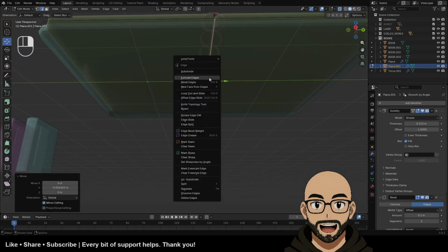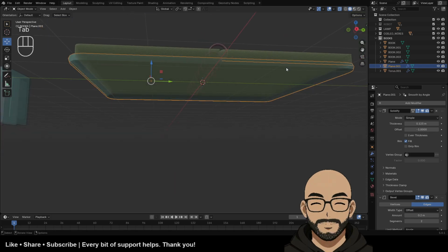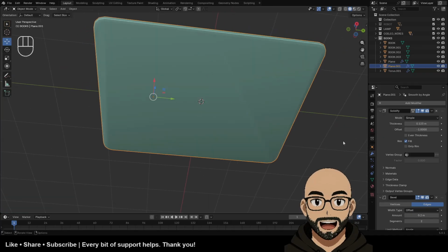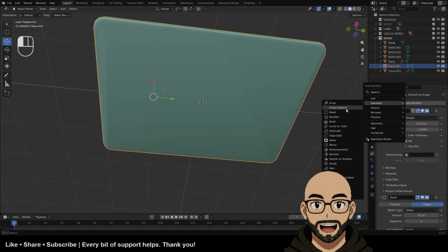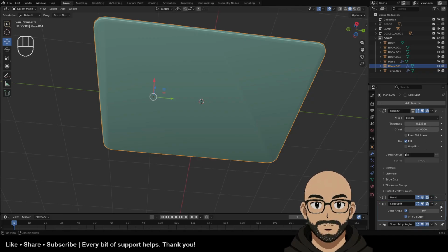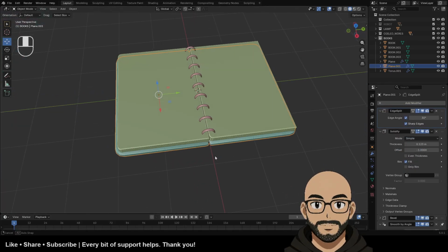And what I'll do is right click, mark sharp. Now, if I come out of edge mode, you can't see anything here, right? So if we go here, we're going to say, where is it? Edge split. Boom. And we want to move this right at the top of our modifiers. Now we've got that split down the middle.